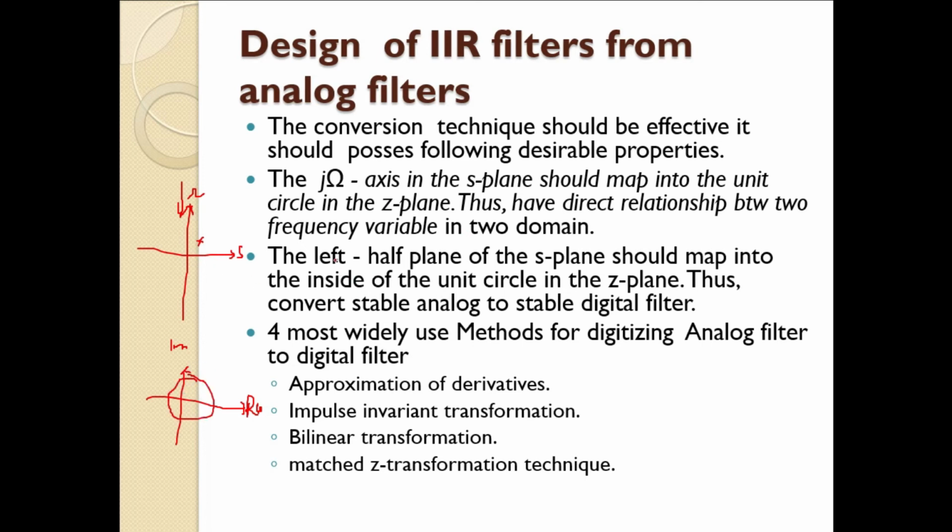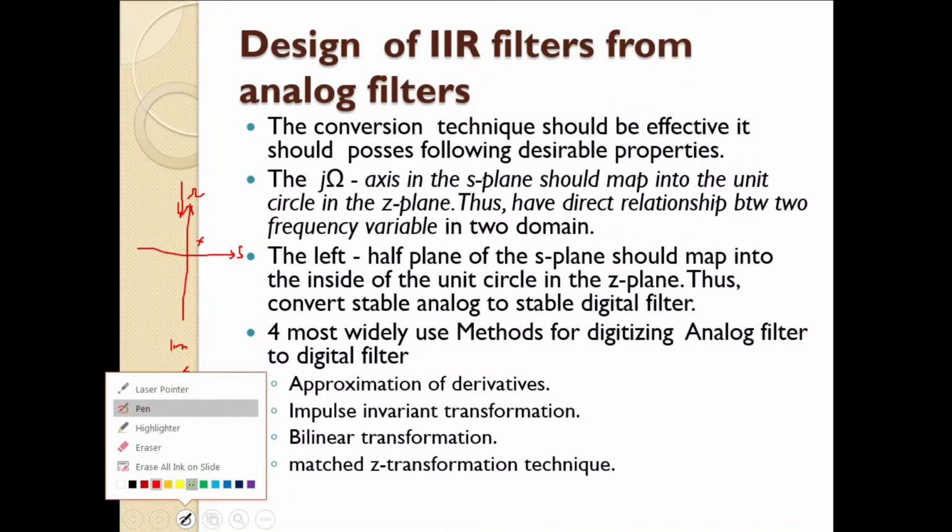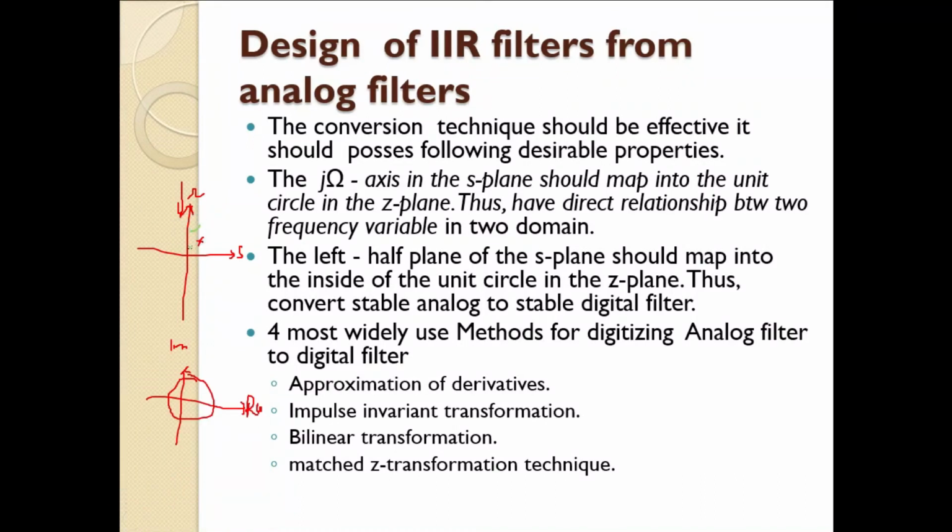The left half plane of the s plane, which means this area, let me use another color, this green color, is mapped into the z plane. So it will map into here, in the unit circle, so it is considered a stable analog.